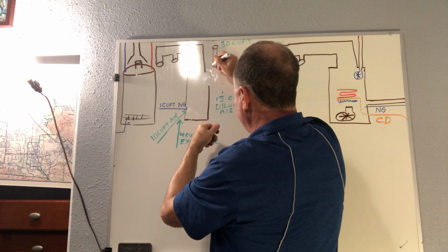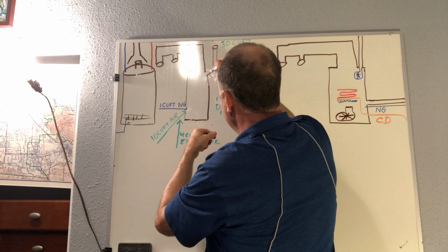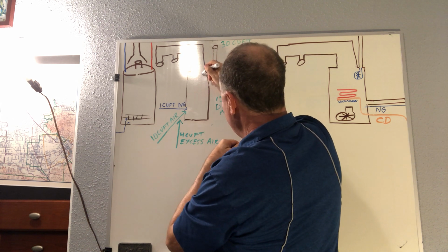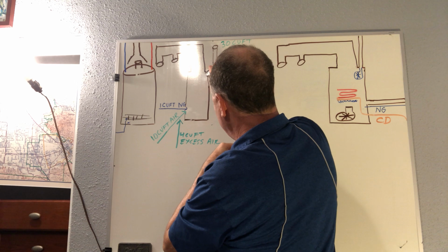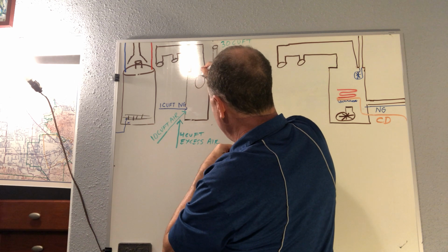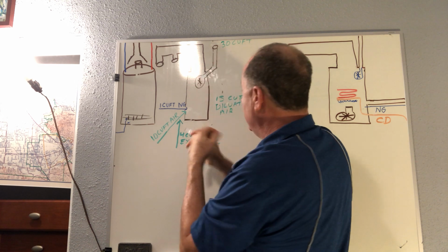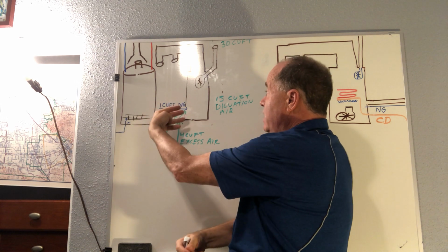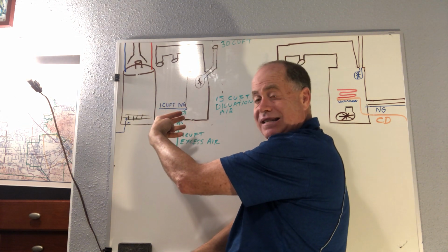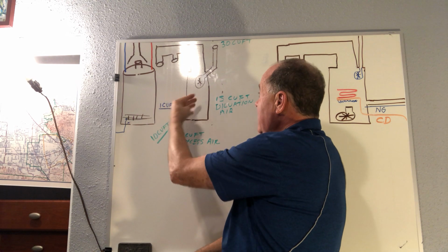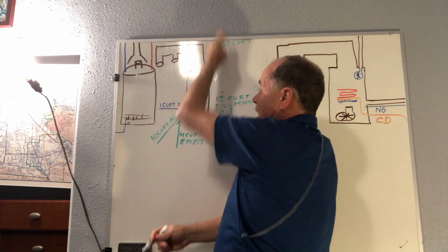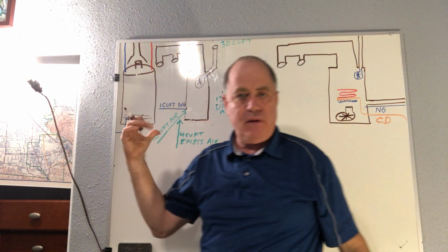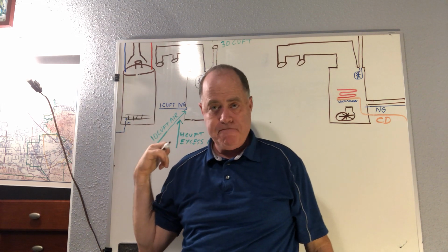You can have a bit of an angle here. That's okay. Coming there like that. And then you're going to have in here a fan, a power venter or combustion blower that's sucking the air and the natural gas in and then power venting it, blowing it out. And most of the furnaces out there are this way, okay?